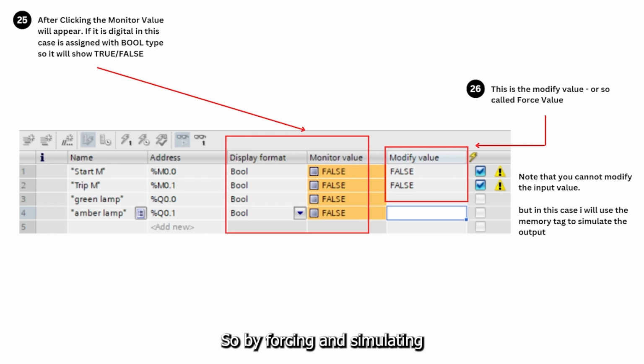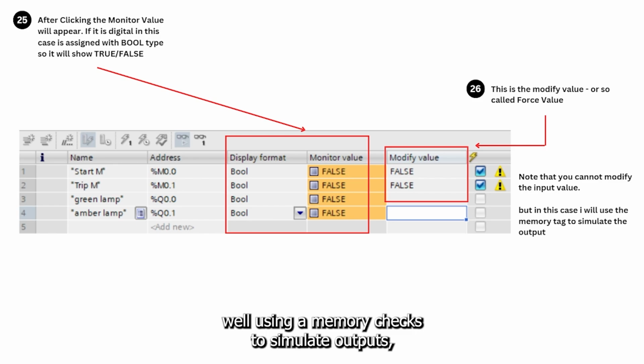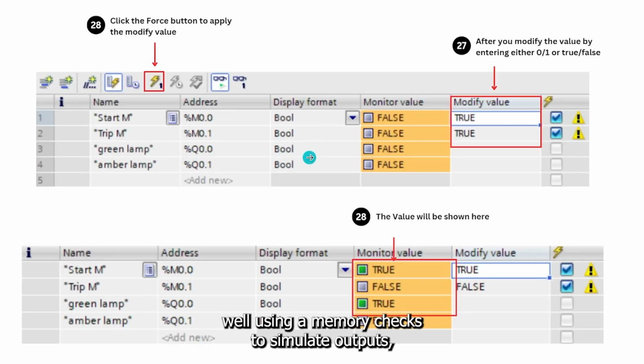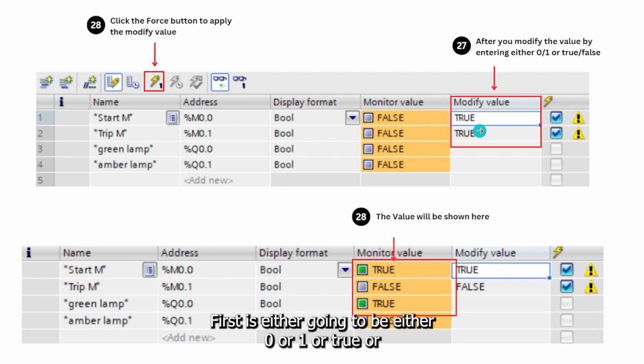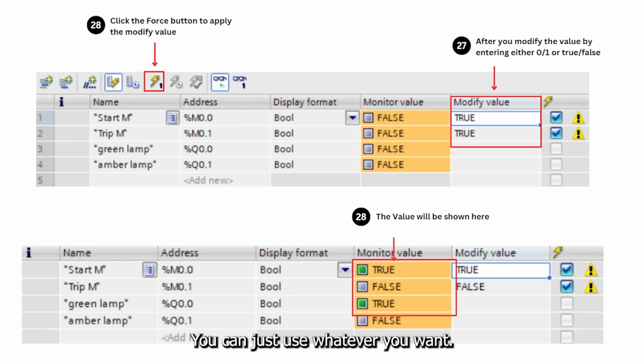So by forcing and simulating values, using memory tags to simulate outputs, click the force button to force the data. But first you have to modify the value. It is going to be either 0 or 1, or true or false. You can just use whatever you want.